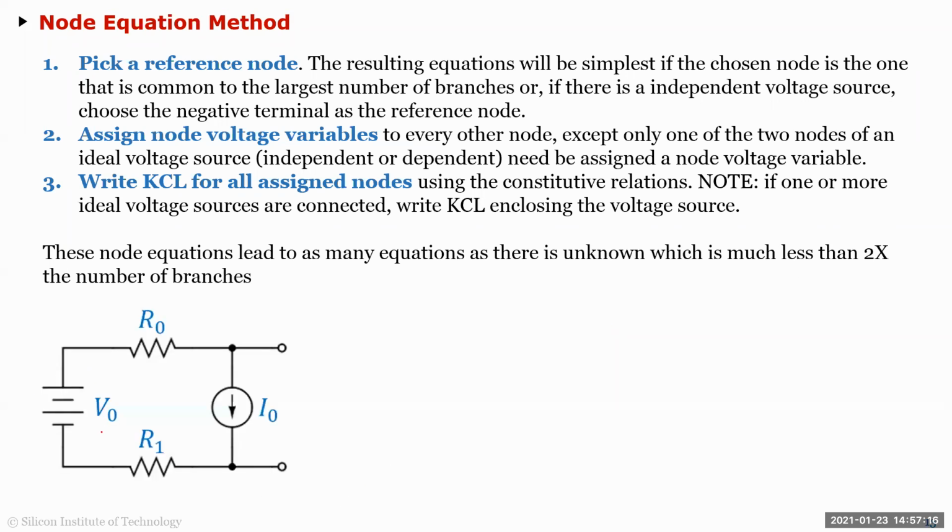If you have this as a V naught, which one would you take as a reference? This one, right? Like I said, you can take any of these as references, but obviously if you take this as a reference, everything will be minus V naught this, minus V naught that, and so on. Whereas this is a natural thing. And that's what I mean. When I usually give this circuit and ask somebody, what's the voltage at this point, and I haven't shown this, obviously everyone assumes this is the ground, but you should not.